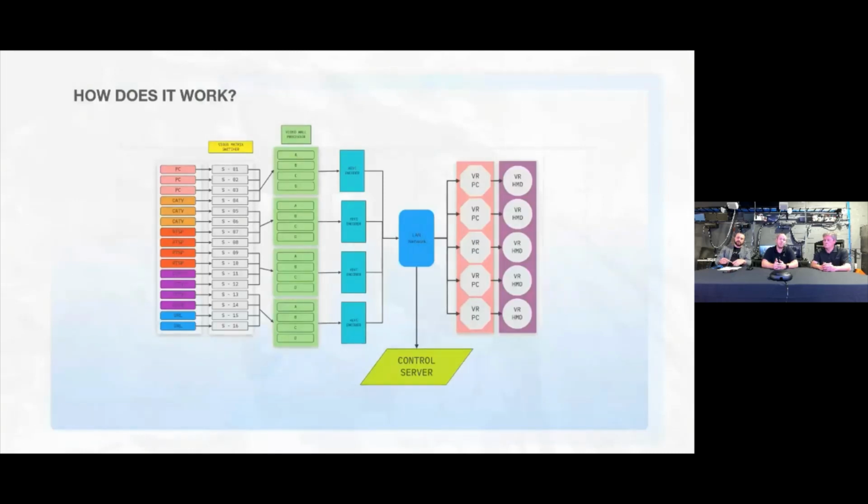But the key to it is that off of this AV network, you hang a control server, and you connect back to the control system. In our lab, it's a Crestron CP4, and basically our application inside the headset allows you to create buttons and to assign syntax to those buttons and to open up a TCP on a port back to that control system processor, and then when you press that button, it sends the command back, and then the control system takes care of understanding what the environment is doing and making the right things happen at the right times.